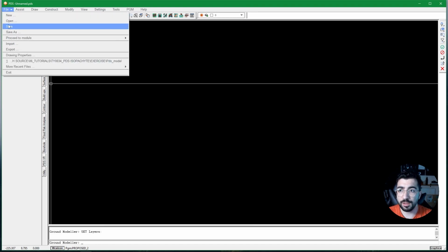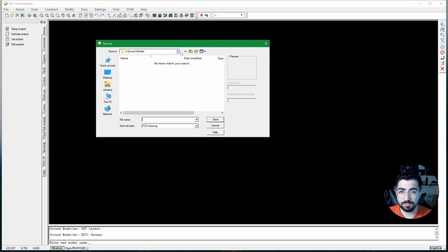If I go File, Save As, and just go into the PDS and CAD templates folder, and just name it CTS Earthworks. And then in brackets, I can name it like band type 1, because that's the main one, let's say. And then I can just say red and blue. Actually, I'll put end loop because I don't know if it will read the symbol. So now I have a template, the PDS Earthworks. I'm gonna make sure that I change the type to PDS model template. So it's the Earthworks band type 1, so basically it's the standard one.